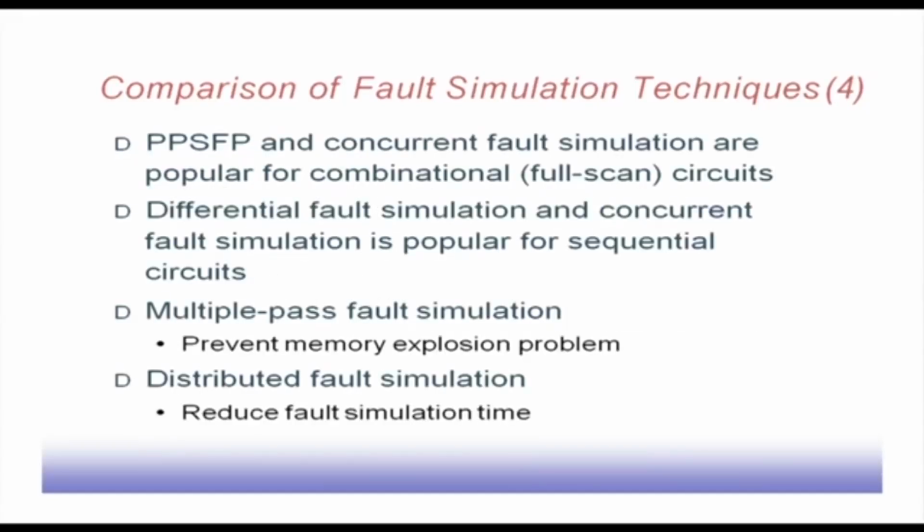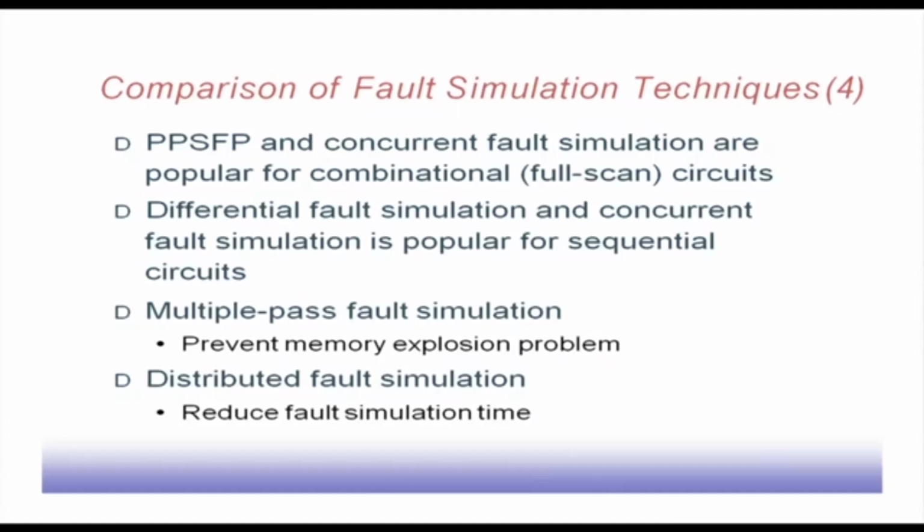PPSFP and concurrent fault simulators are popular for combinational circuits and full scan circuits. Full scan means a sequential circuit where all flip flops are connected over a scan chain. So, that becomes a full scan circuit. For those cases, PPSFP and concurrent fault simulation are popular. Differential fault simulation and concurrent fault simulation are popular for sequential circuits.